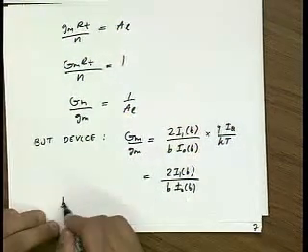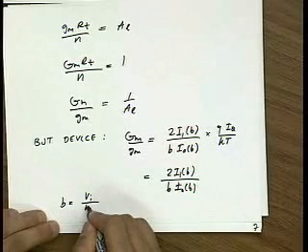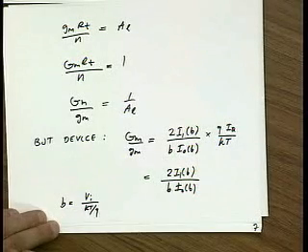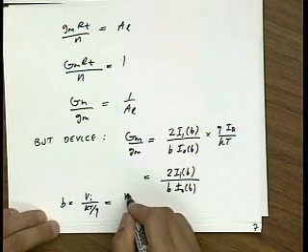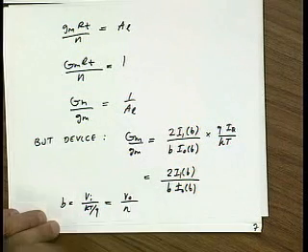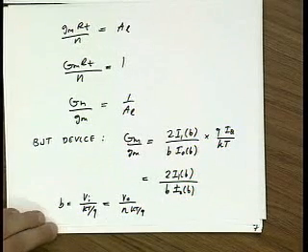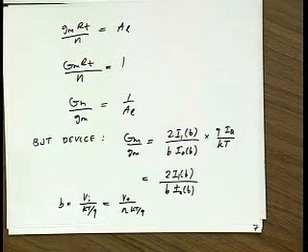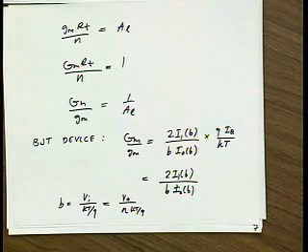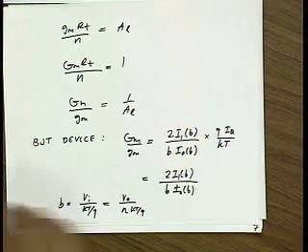And remember, B is the input normalized to KT over Q, which is basically the output divided by N, KT over Q. Okay? So now you guys have the recipe to go home and design a BJT-based oscillator, because these functions are well known.